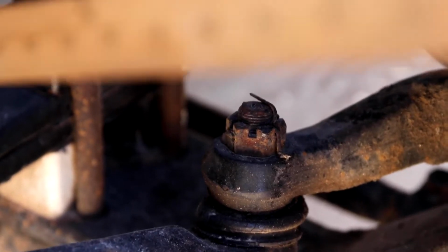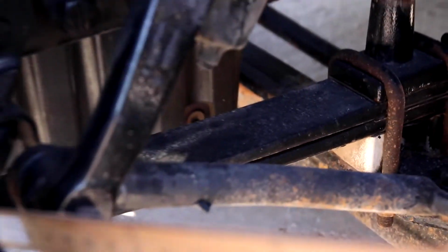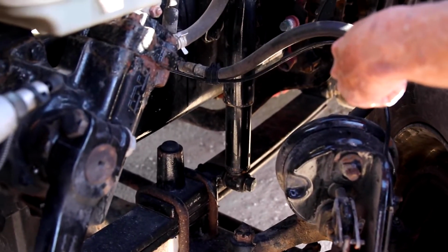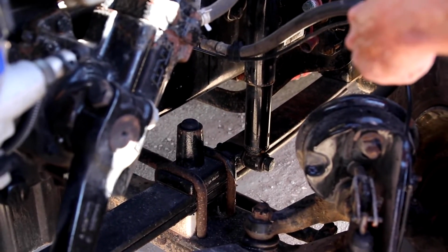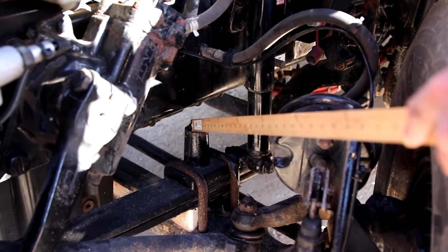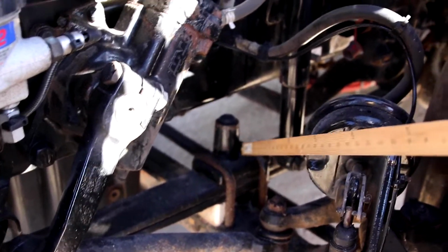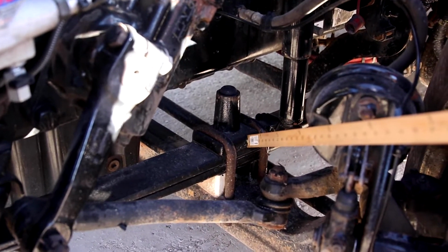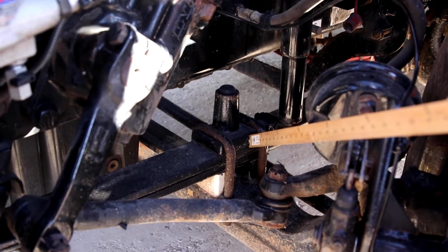Next, we have our suspension. You have your front and rear spring hangers and mounts. They are mounted securely to the vehicle. They are not missing, damaged, or broken. You have your middle mount, which is right here. It is not missing, damaged, or broken, and it's held in place with 2 U-bolts and 4 nuts.